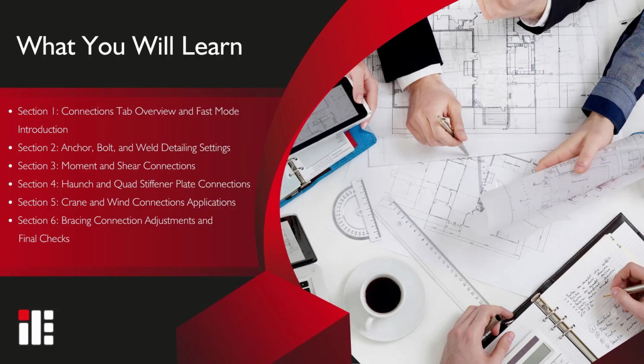This tutorial introduces the Steel Connections tab in ideCAD Structural. It begins with fast mode for automatic connection generation and continues with manual detailing of base plates, bolts, anchors, and welds. Moment and shear connections are applied to beam-to-column joints, while haunches, stiffeners, and splices enhance structural capacity.